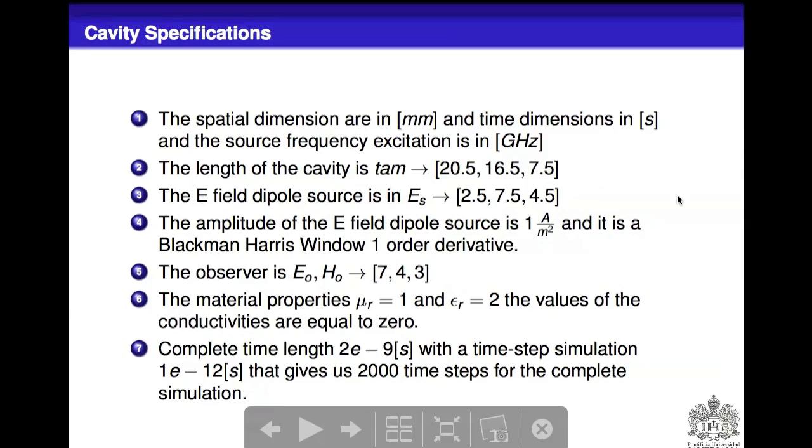As you can see, all the material is surrounded by PEC, and the inner material is a resonant material that has one relative permeability and two relative electric permittivity in both cases. Then the values of the conductivity should be 0, as we said previously, to neglect the attenuation behavior at the end.